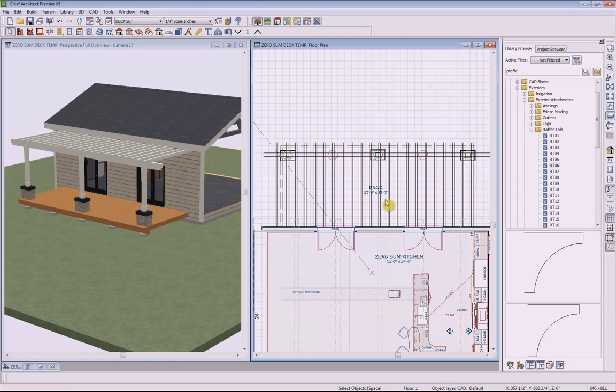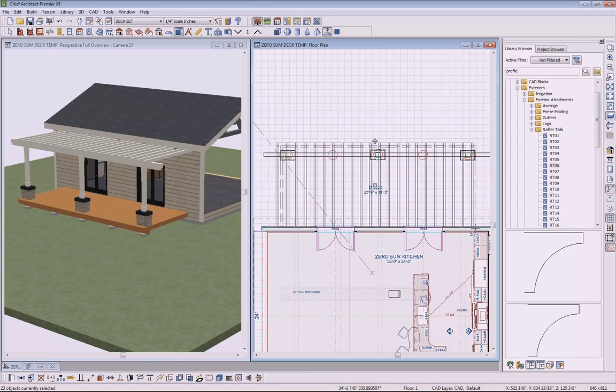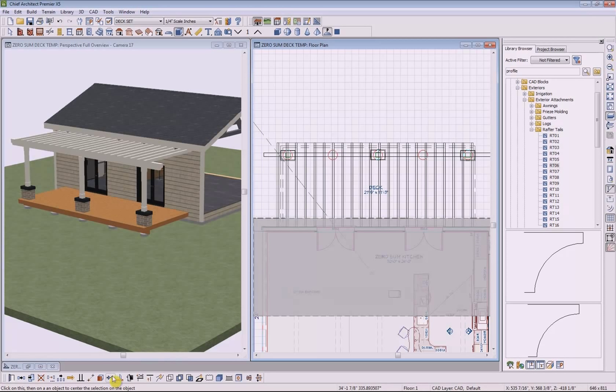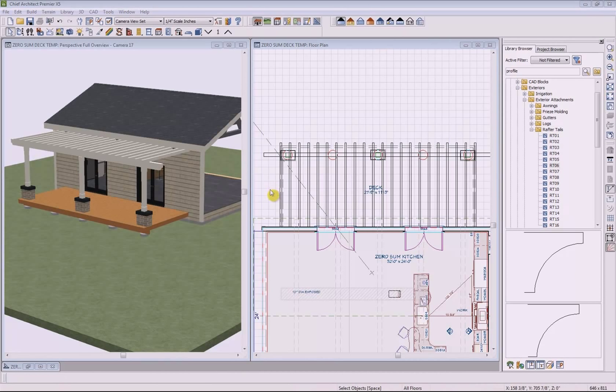Okay. And then of course, if we want to, we can center all those right on the center of our deck area. So if we go up to our polyline tool, we can hold the Shift key down with that tool selected, and we'll grab a marquee around all of our trellis members. And when we do that, it only selects those trellis member polyline solids. And we can go down just like we centered before, hit the center key, and come up and center all those trellises right in the middle of our deck area. Okay. So our trellis here is pretty well complete.